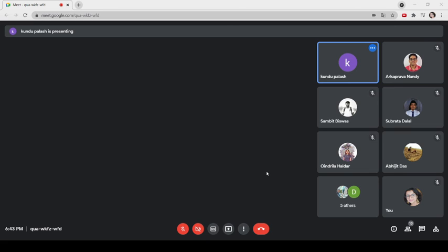So this is the diagram of the counter mode. When the C/T is set to 1, the timing signals come from the external pins, that is T0 and T1, under mode 1. This is for mode 2 operation. So counting programming. And these are the functional diagrams, which are very important, not the circuit diagram, showing how the external signal gate can enable or disable the timer operation.